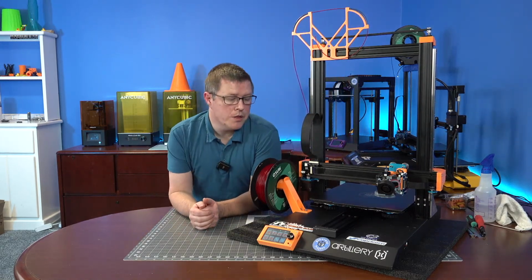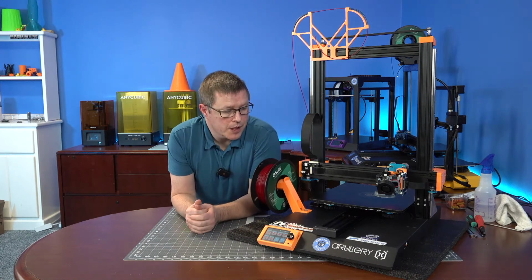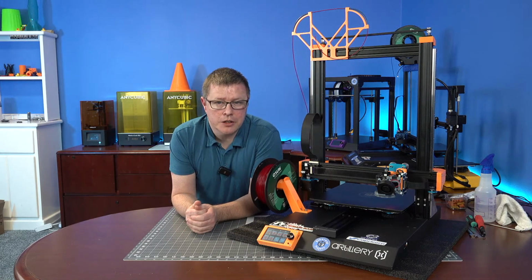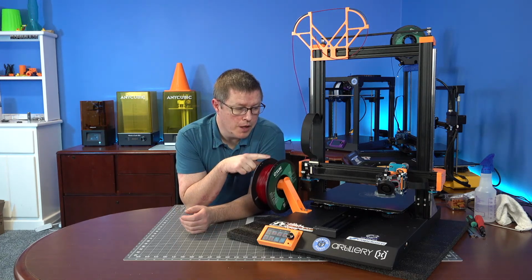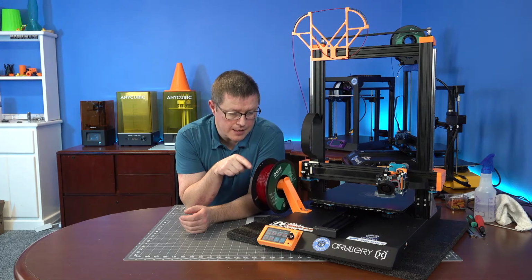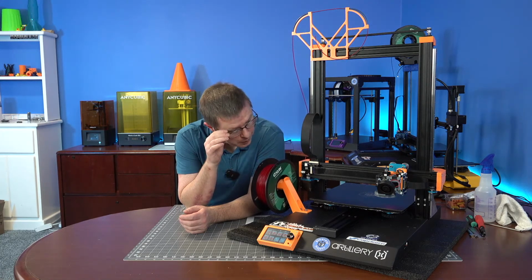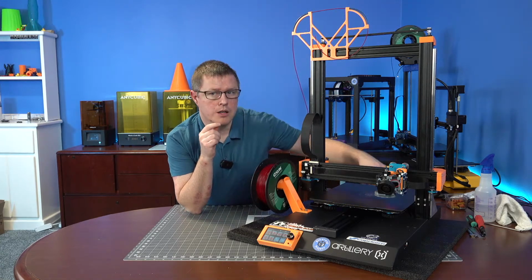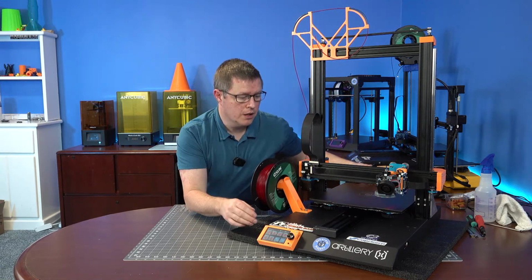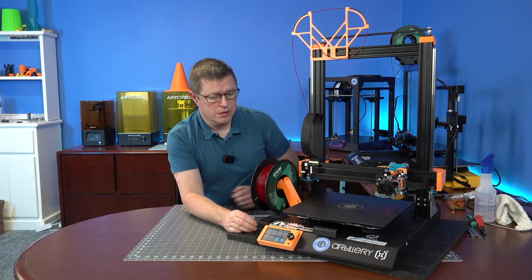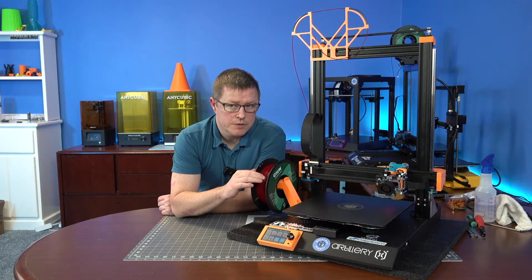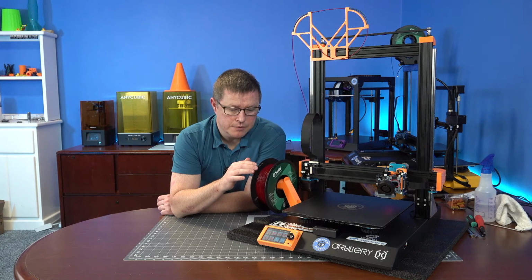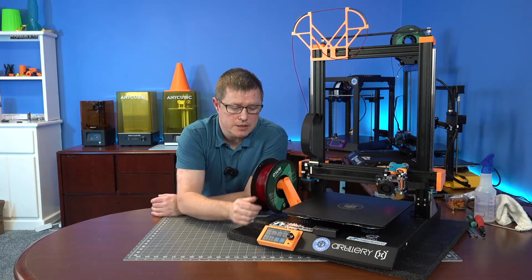One thing with these is that the glass is not a very good conductor of heat compared to aluminum, so if you run the leveling as soon as it says it's warmed up, it's not fully warmed up, and your corners will end up getting tighter on you because that heat hasn't transferred to the corner just yet. So if I want a really accurate surface map, I'll let it preheat for like 5 or 10 minutes so it really heat soaks the glass.